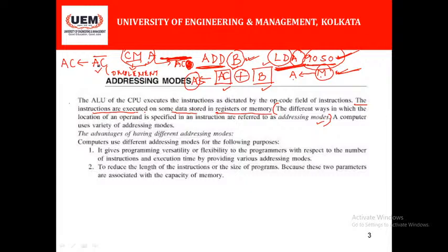So this is one approach for hiding your operand specified by the definition of your instruction. Let's take another example, say MVI A, 55H. In this example, 55H is the hexadecimal data. We are specifying this hexadecimal data directly inside the body of the instruction, or inside the definition of the instruction. What we are doing is transmitting the 55 data to the accumulator register.